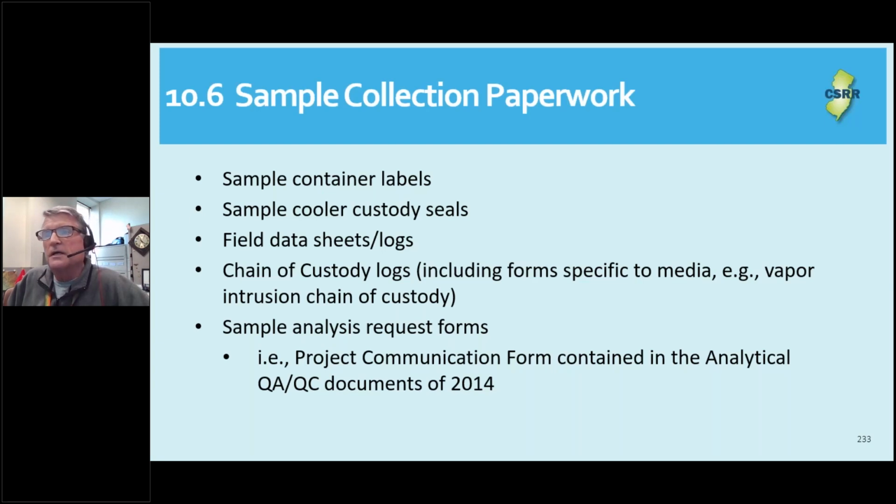Some are required to document the identity of the field sample, which method is used, which parameter is a remediation driver, who relinquished and received the sample, and whether the sample was accepted by the laboratory. You get the message about the cradle-to-grave documentation for sample collection and shipment. Next slide, please.